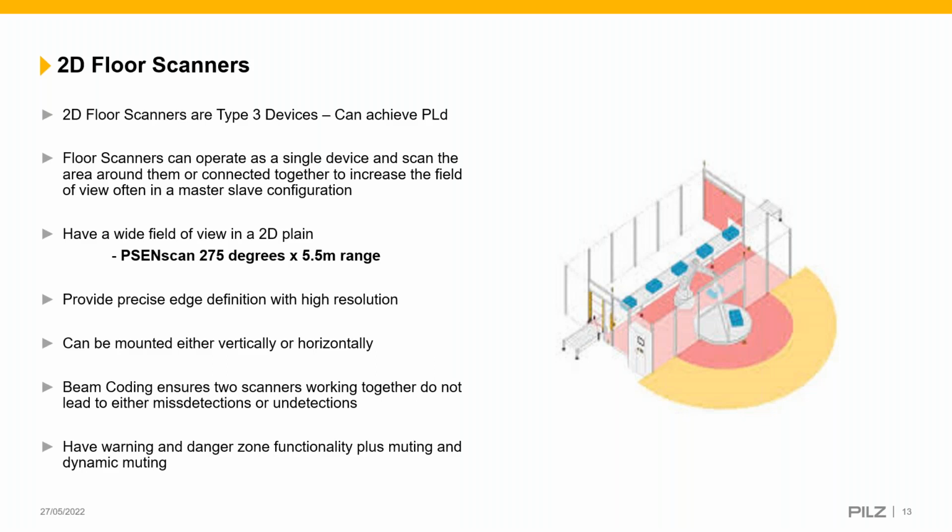And the scan times you can trigger dependent upon the number of scans. So it would generally, most commonly, be 2 scans. It picks something up the first scan, it will look back round. Is it there again? Yes, right, I'm going to trigger the light curtain, turn off the outputs. But you can increase these to 2 or 3 or 4.